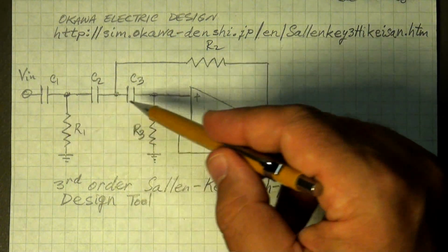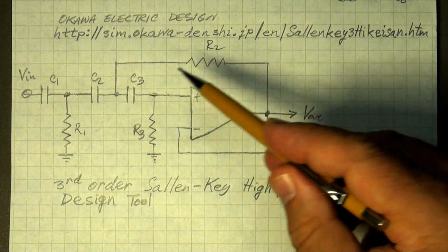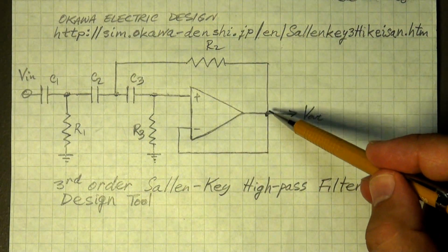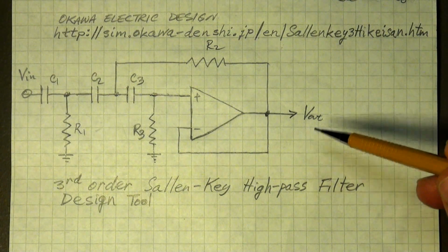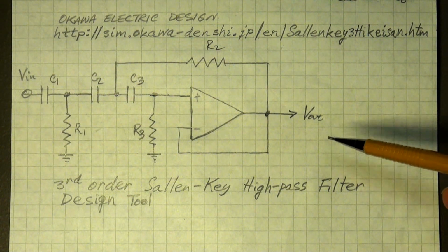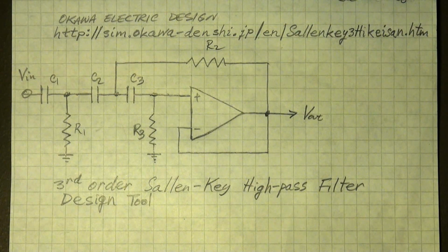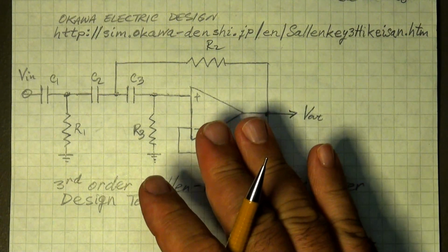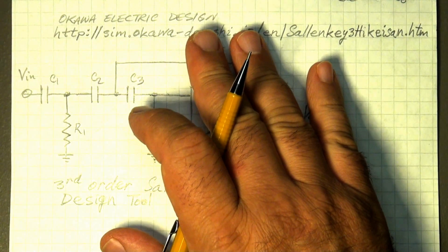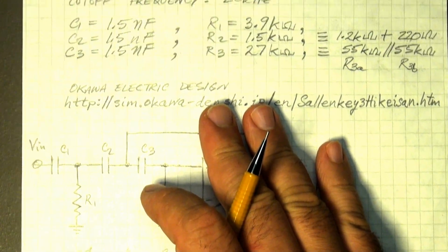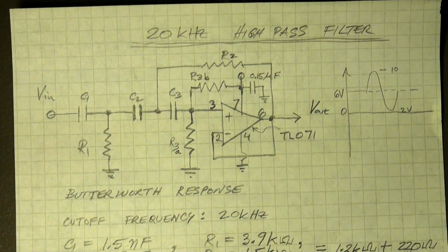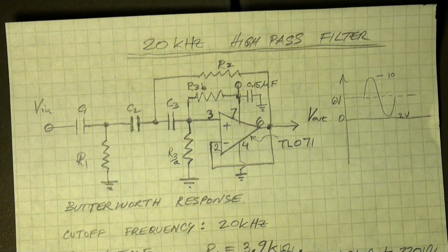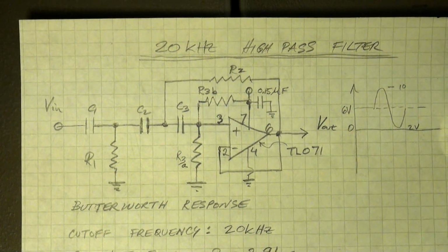Positive, in this case it's in the positive feedback network, and the negative feedback is unity gain. So starting off with the textbook example, I developed my own version of it to accommodate the DC biasing that I need to incorporate to make it work for a single power supply.